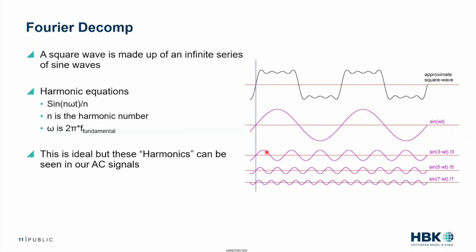So when we talk about reactive power, and also RMS values, we need to discuss the reactive power of what frequency band, the apparent power of what frequency band, the RMS of what frequency band. And this is the difference, and this is why filters become so important. Because if one instrument has a 3 kilohertz filter and one has a 30 kilohertz filter, you're going to see different values, because these harmonics have their own phase distortion. They have their own reactive element. They have their own RMS element that's getting added into the total. That gets even worse when we look at switching. And again, we'll get there.